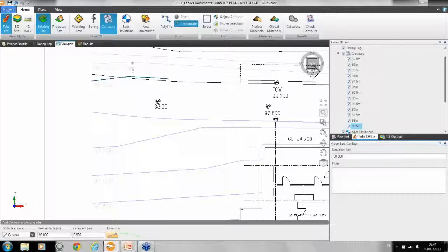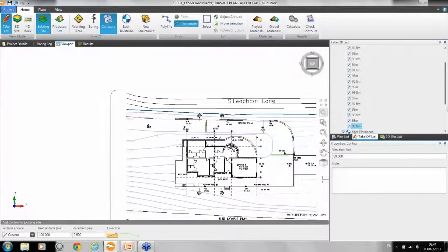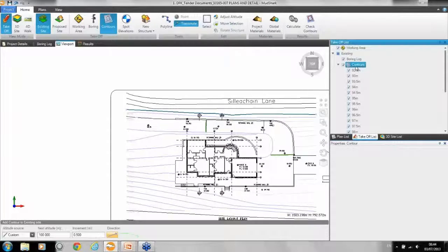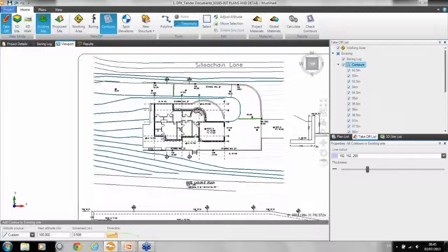Okay, so you can see very quickly you'll be able to measure your existing levels, and you can see that all those contour lines now are converted to give us takeoff lines directly from a PDF drawing. So no more are you using the takeoff ability and having to polyline it. It should improve your times 5-10 times depending on the level of the PDF drawing.